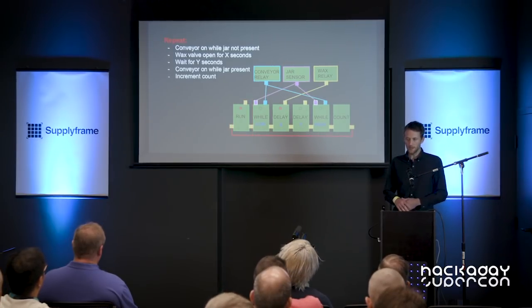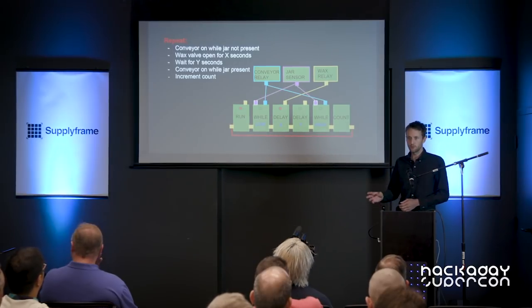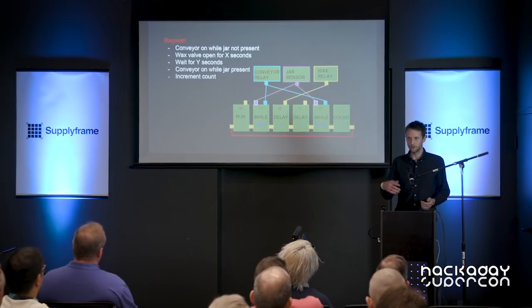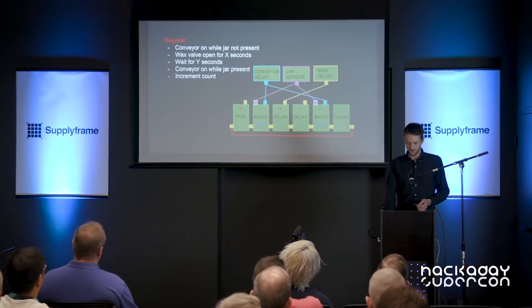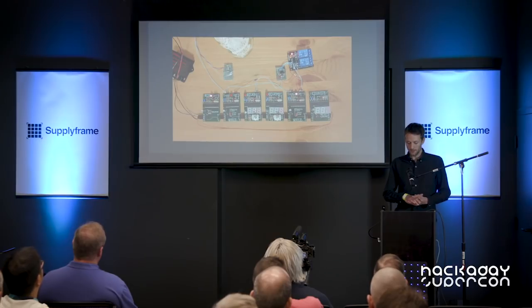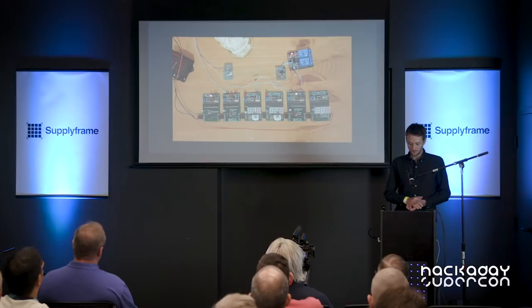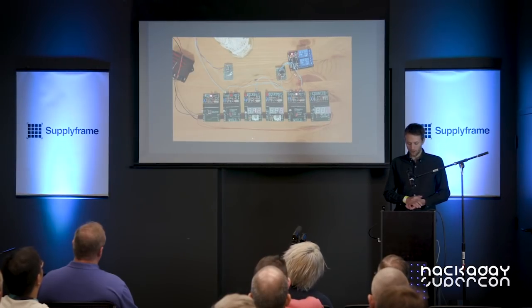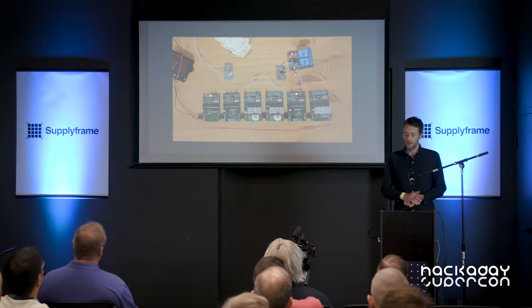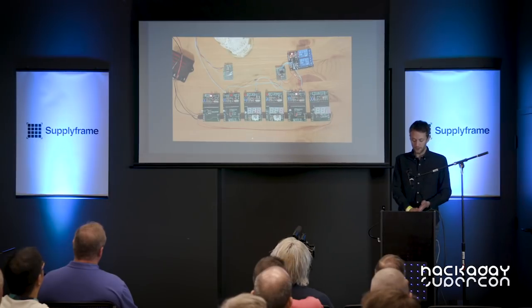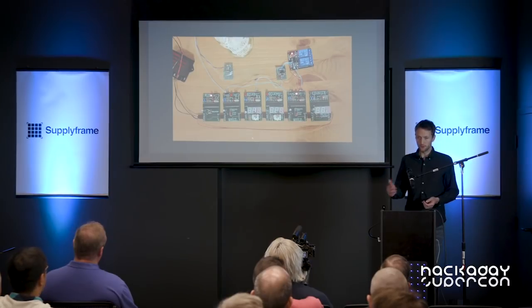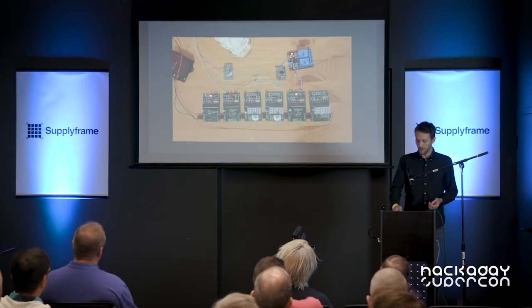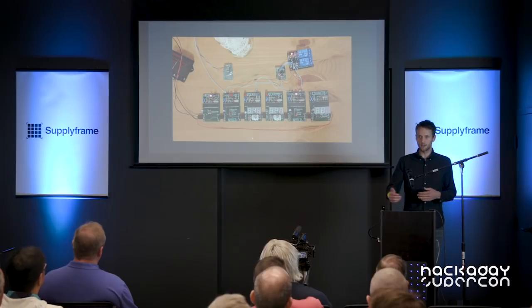And we connect the output trigger of the last block to the input of the first one, and this allows this whole thing to iterate in a loop again and again. And here is the complete solution assembled on my kitchen table. Looking at this, I can immediately see that it has been configured to dispense wax for 12 seconds, then to delay for 3 seconds. I can see that it has already filled 19 rows of jars.